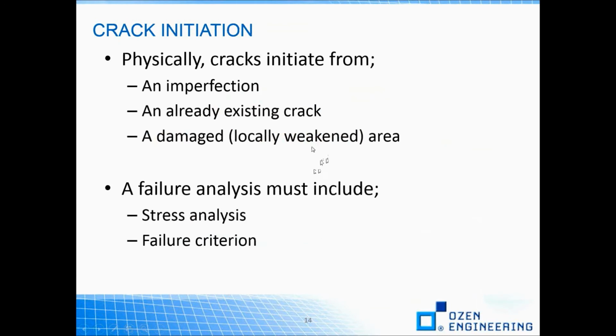As we have mentioned before, crack initiation takes up little of the overall lifespan, and still it's an area of concern for determining structural reliability. It is known that cracks initiate from an imperfection, an already existing crack, or a locally weakened area. And in such cases, a failure analysis must include the fracture mechanics analysis. nCode's strain-life is one working method that we have at present for predicting the so-called life to crack initiation.